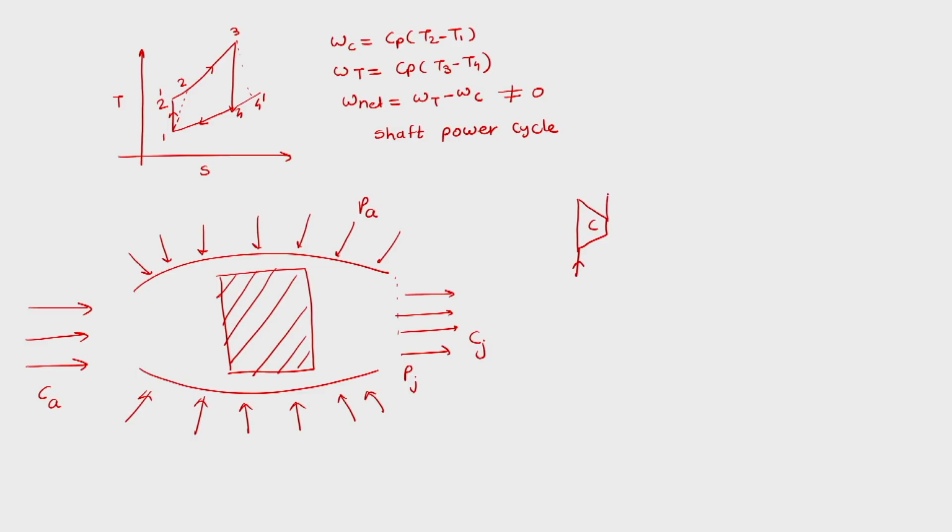in which air will come, then it will go into the combustion chamber, and then from the combustion chamber it will go to the turbine. This turbine was running the compressor. But here we had the turbine connected to the generator also earlier. So, there was W net given to the generator, Wc was given to the compressor by the turbine, and obviously there would be some transmission losses, so on both sides it has to give more. So, the turbine has to give more work than Wc to the compressor, and the rest of the work it will obviously give to the generator.